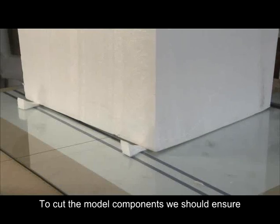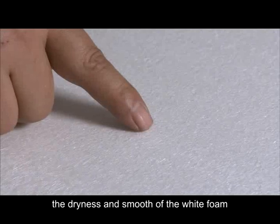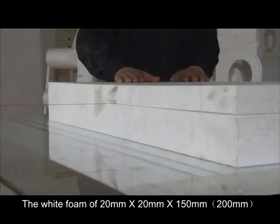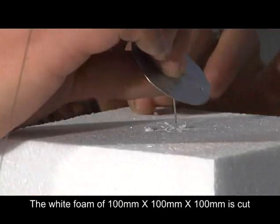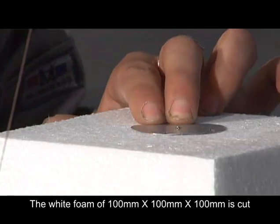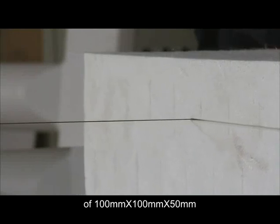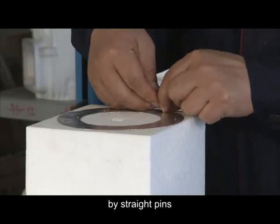To cut the model components, we should ensure the dryness and smoothness of the white foam. The white foam of 20 mm by 20 mm by 150 mm, 200 mm is cut into a diameter 20 cylinder. The white foam of 100 mm by 100 mm by 100 mm is cut into a circular truncated cylinder of 100 mm by 100 mm by 50 mm. The model should be fixed on the foam board by straight pins.